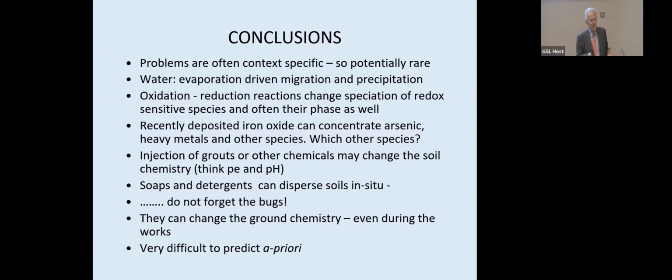But I think it was basically water drawing, because bricks contain quite a lot of gypsum, which is that efflorescence you see on brickwork, and you can dissolve it off with acid. So I suspect that was being wicked up into the mortar, being probably slightly finer pore size. So the water went there, then evaporated from it, and deposited this strange double salt. I think it was probably potassium calcium.